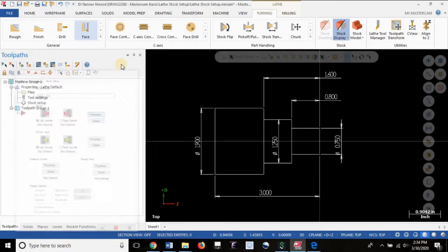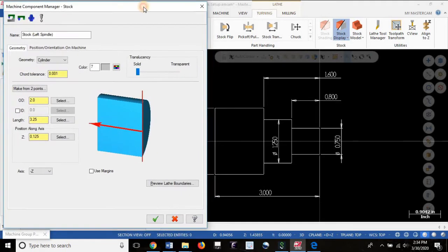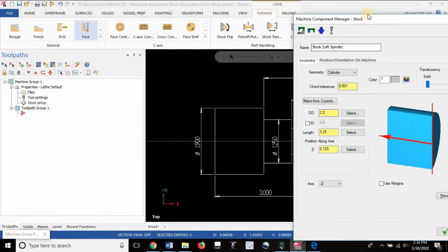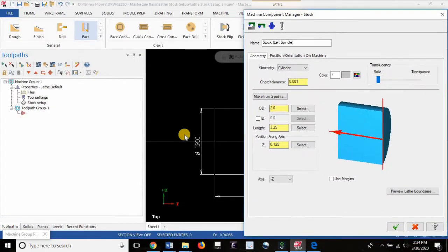And what we want to do, using this menu on its most simple functions, is to represent an outer diameter of rough stock that is greater than the finish size. So if you have a 1.9 inch finish size, it stands to reason you'll make that out of a 2 inch diameter workpiece. So we want to accurately reflect that number right here.